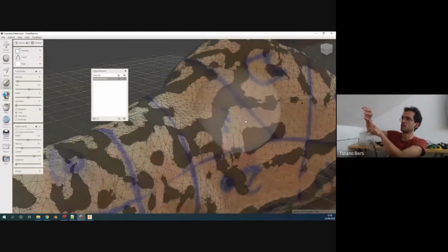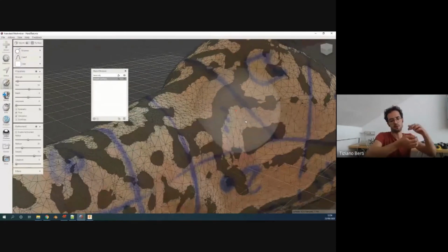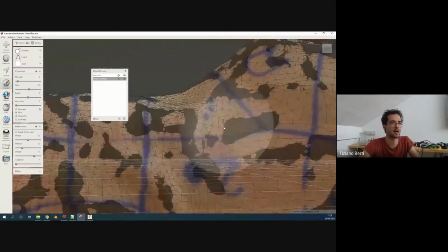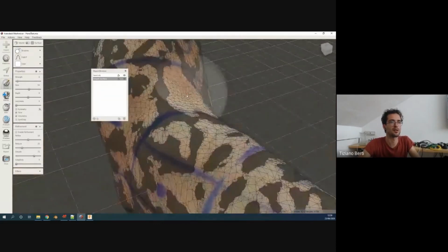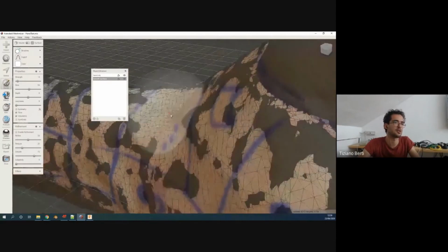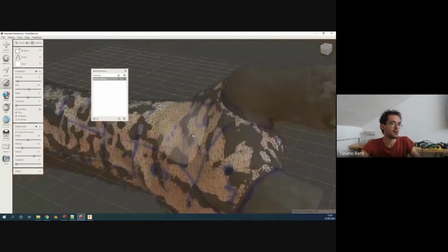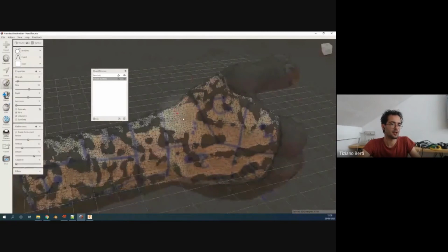And testing the brace, this kind of part that pushes into a kind of defect you have is not so good for ergonomics. So I'd like to smooth this part out. So I want to pull it out a little. You can modify the mesh whenever you like, and it's easier to do that before creating those kind of breathable structures, and also before giving a thickness to our surface. So this is the moment where I correct the mesh.